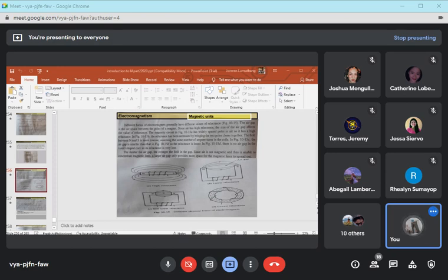So take note: the shorter the air gap, the stronger the field in the gap. Since air is not magnetic, it is unable to concentrate magnetic lines. A larger air gap only provides more space for the magnetic lines to spread out.